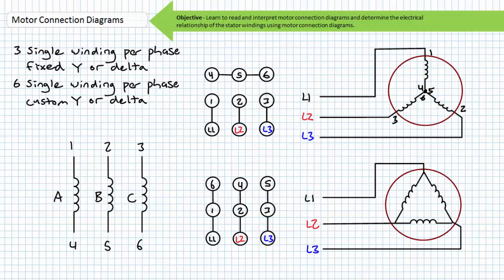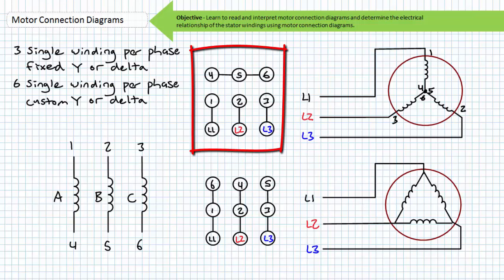Terminals 1, 2, and 3 are left to be connected to the three-phase AC source, where direction of rotation is determined by the phase sequence. Given nodes 4, 5, and 6 forming the central node of the Y are now accessible, a technician has direct access to the voltage across each winding without resorting to any mathematical trickery for power consumption calculations. The motor connection diagram might illustrate a 6-lead Y configuration using a diagram similar to this.